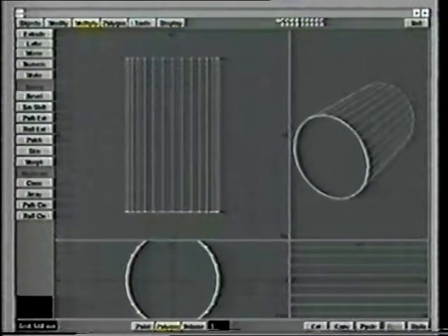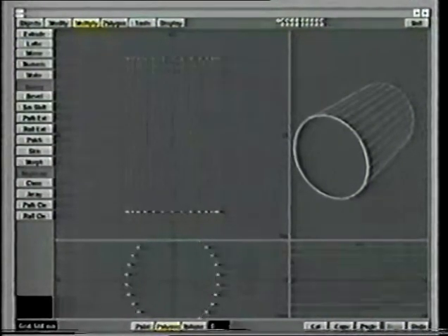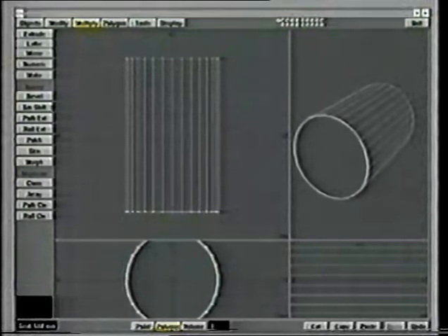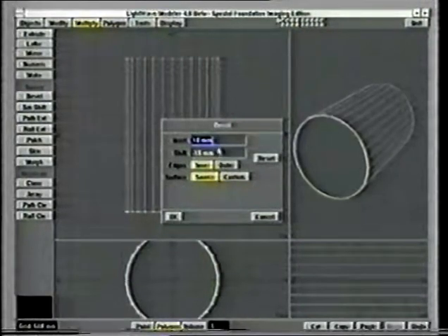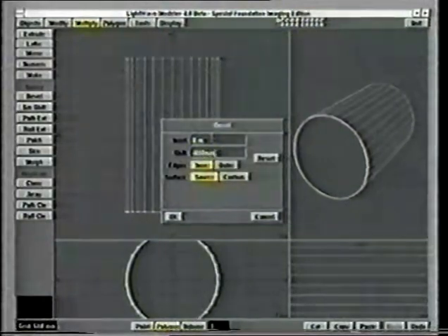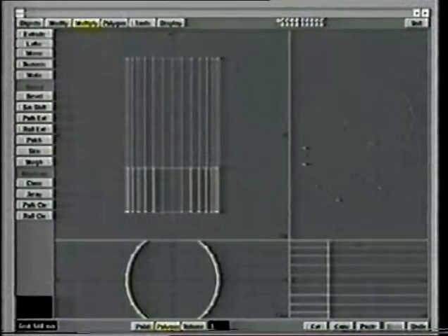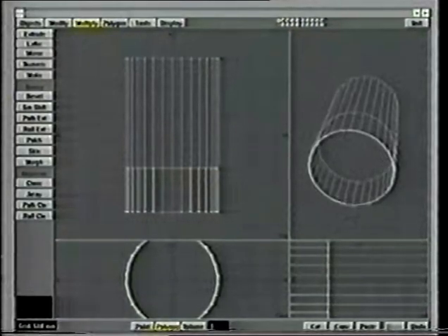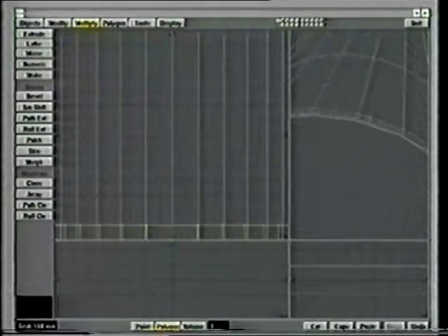Okay, and again I cut it and paste it, reselect it, and one more just to get the inside here. So I want an inset of 0 and a shift of minus 800. And there you go. Okay, as you can see, you've got the cylinder with the hollow front end, but it definitely has a thickness to it. As you zoom in closer, you can see that that edge will show up.